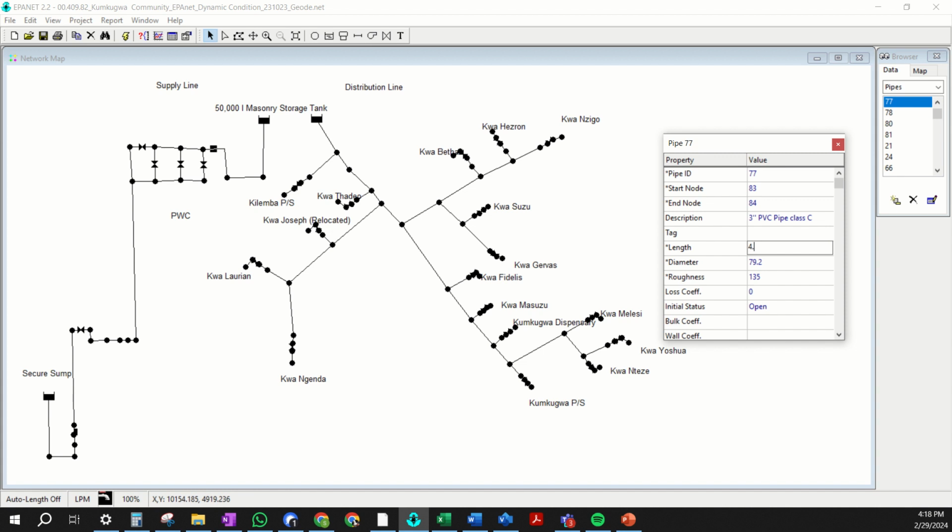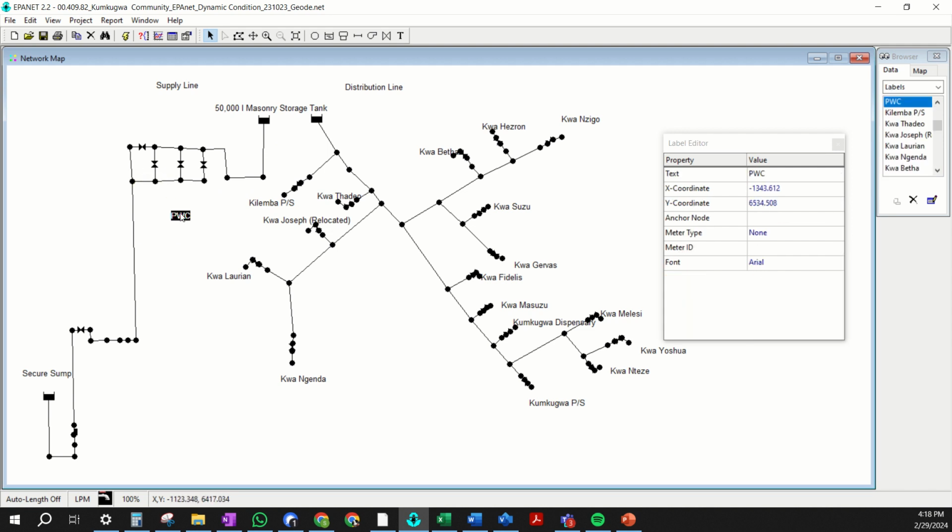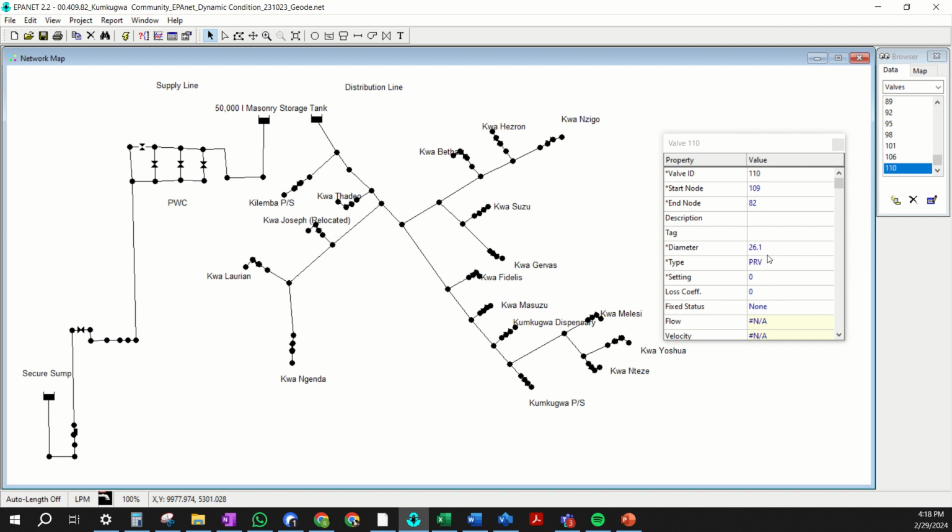So I would make this 4.5 meters long, add some extra length, and I'll also put a loss coefficient to cover all the elbows and things inside the treatment house. I'll use a loss coefficient of 6. Okay, then you have this pipeline going over to the tank and this pipeline up to the tank. So now the last thing to do is do the details of the bypass valve.